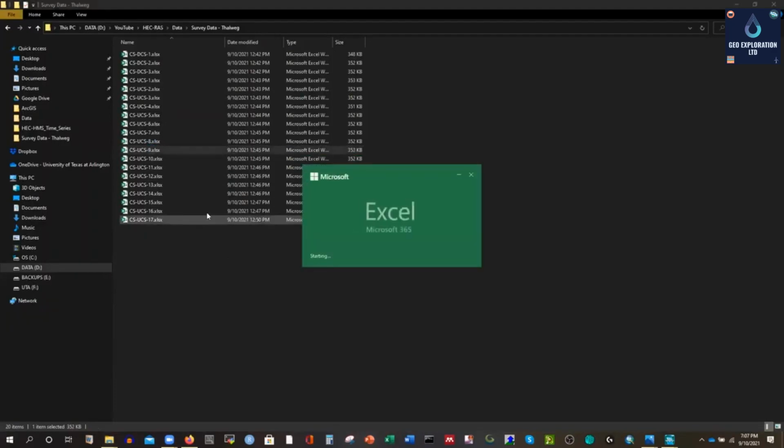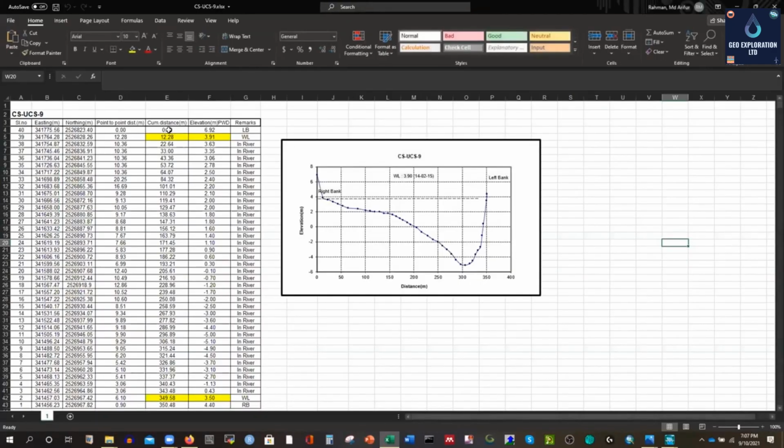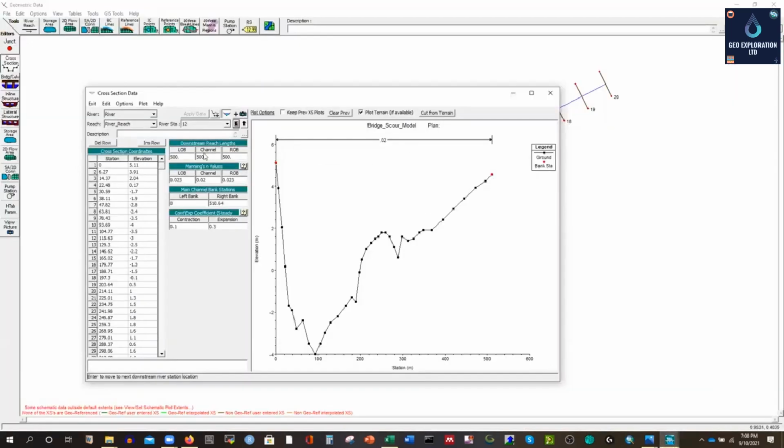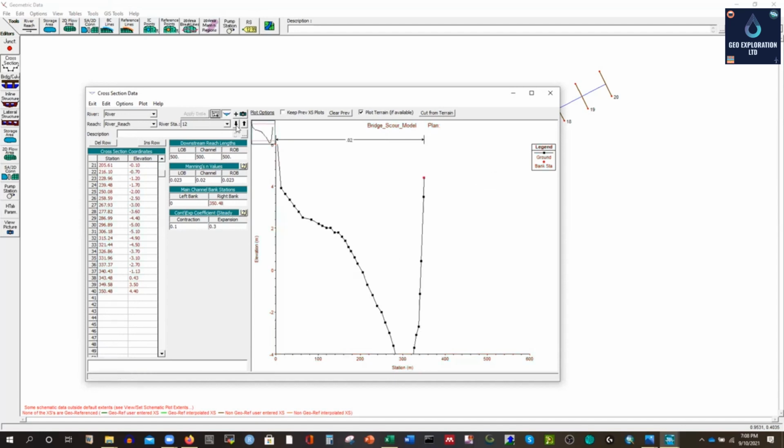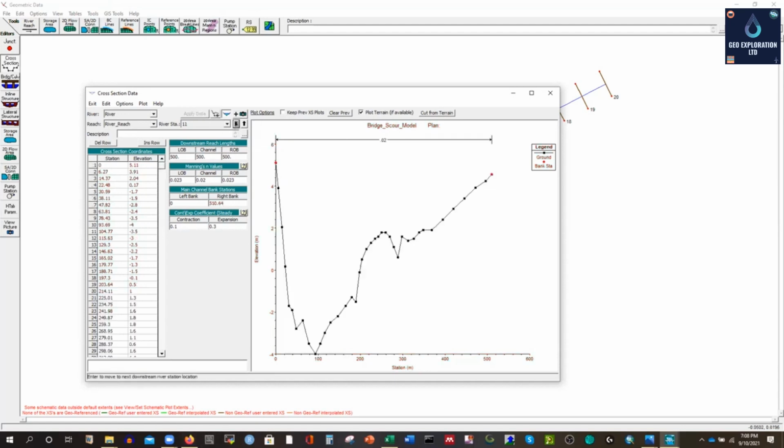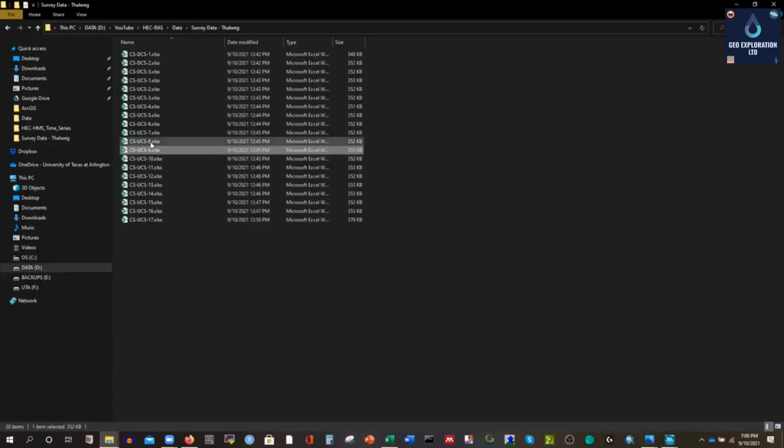And then here I'm in number 9, and I'm copying it again, because it depends on the river cross section. You can see at the same time how it looks, right? The same cross section we have here, and we can see we have the same cross section there. I'm copying and pasting at the same time, and again I'm just replacing the right bank, because the left bank is always at 0. Okay, so which one is next?